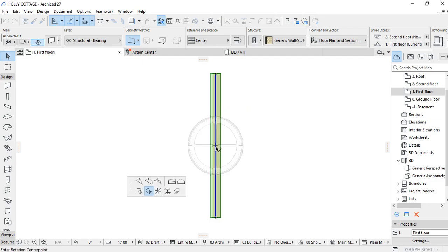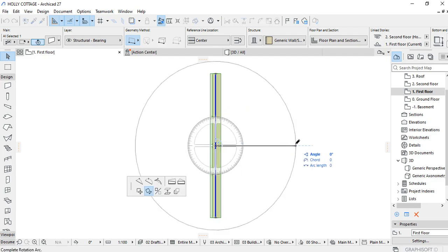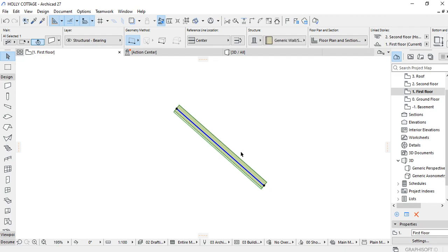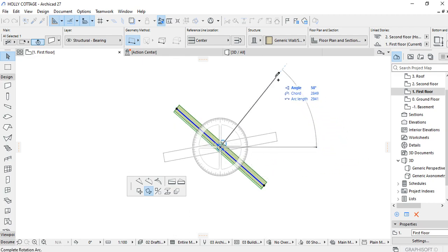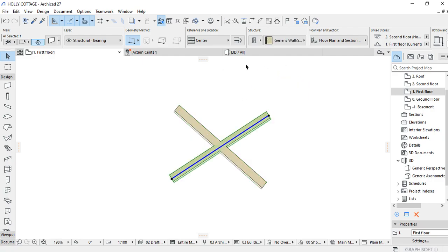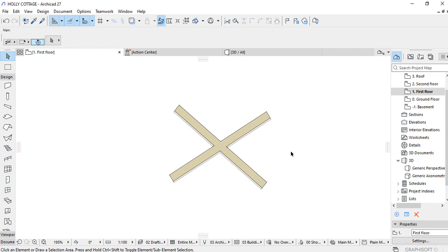So again, when you press here, choose the angle of rotation, then you can press tab, then you are able to insert the angle to rotate it, and again it's rotated. So to rotate it, maintaining the same element to create a copy, again, as you're in the command, you can press the Control button. It brings the plus sign. So you can first draw the line of rotation. Then after, you again now draw the second point of the angle of rotation. So now you remain with your